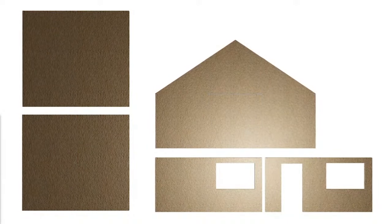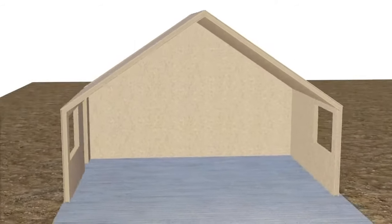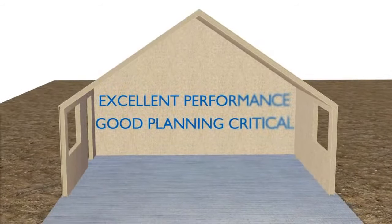There is, however, scope for problems to arise if project requirements are not fixed and tolerances on site are not achieved. SIP homes must be designed and manufactured well in advance of their arrival on site, and it's very difficult to account for any changes during the build process.